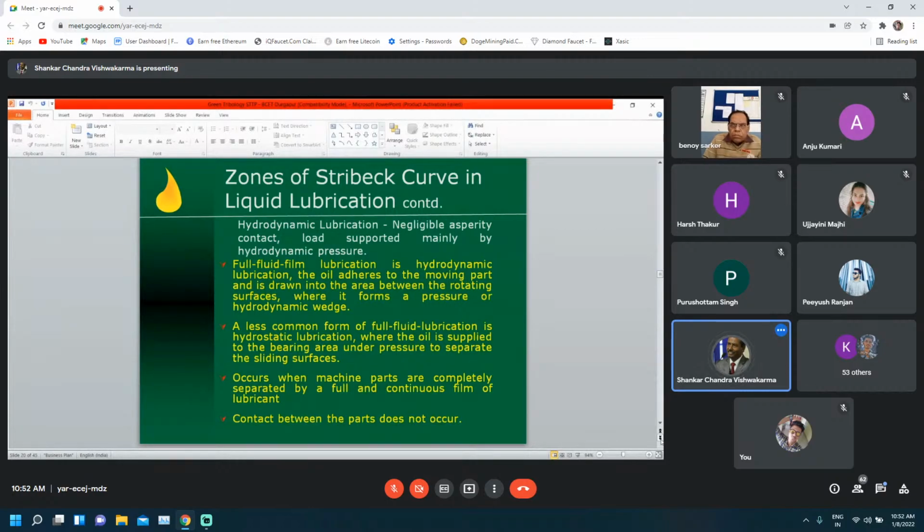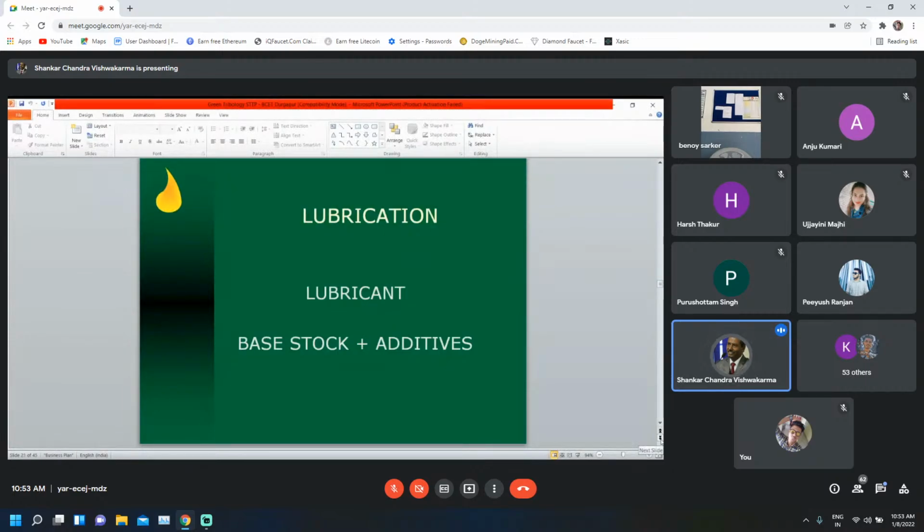It's very uncommon. But for machine parts which we use in general, particularly camshaft bushings, crankshaft and crankshaft bearings, we need a very good lubricant so as to work properly, and the lubricating system should work properly so as to maintain the hydrodynamic lubrication.